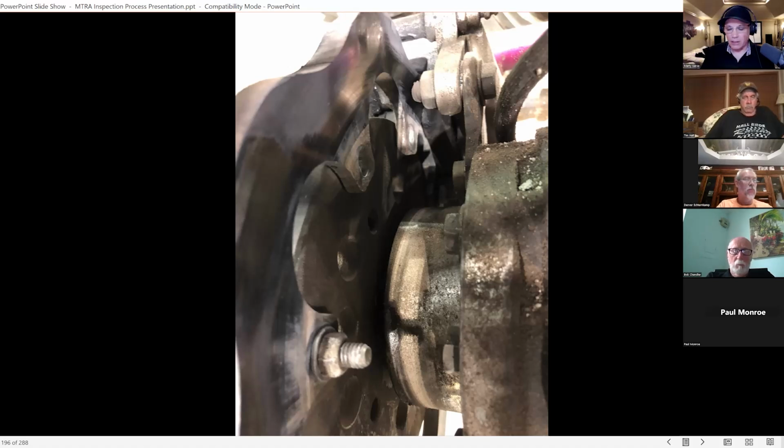There are rotors, and I don't think I put that in this, but I recently noticed that a couple of trucks had rotors that were threaded, that didn't have nuts, where the bolts just screw straight into the rotor itself. I wouldn't trust that. Just like the throttle linkage, I think it's important that we go all the way through and nut it, because there is no way to have any sort of resistance like that. In other words, if it's designed to be threaded, you're going to use Loctite, and it's going to be useless. It needs to have a lock nut of some sort.